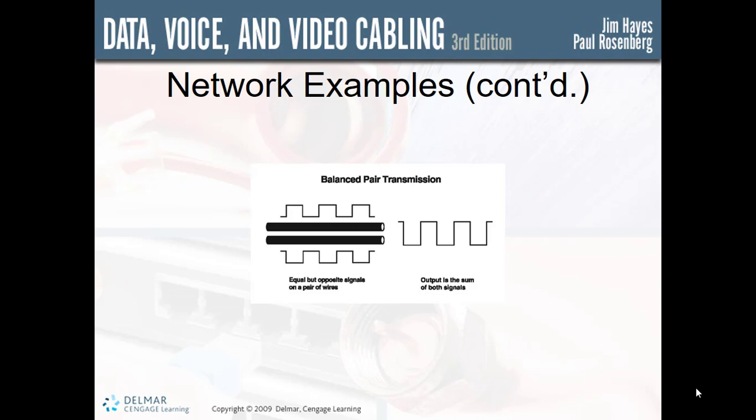Some cables have been offered with a high performance guarantee only on 2 of the 4 pair, but these cables can be troublesome if the cable plant is ever upgraded to high speed networks. Although most networks only use 2 pair of the 4 pair available, it is not recommended to use the other pair for telephone or other LAN connections. However, adapters are available to allow multiple signals to use a single 4 pair cable.